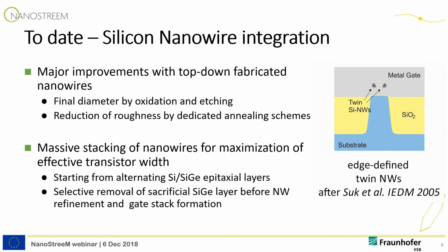And on this picture on the right side, you see that there are certain techniques where you can produce nanowires at the edges of some polysilicon features by some edge-defined techniques like edge-enhanced oxidation, and people are very skilled in and develop very tricky schemes to carve out nanowires out of existing features that are already available in the silicon technology.